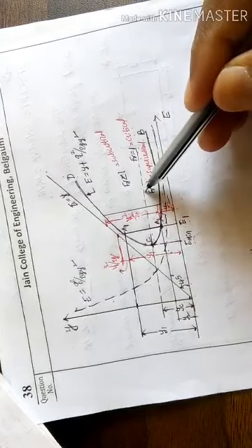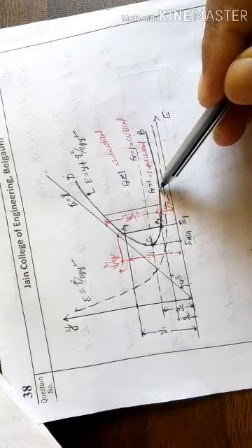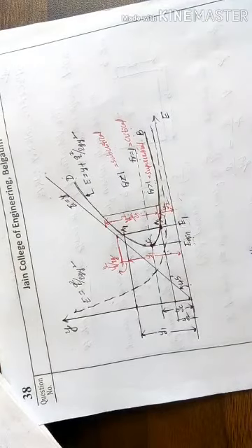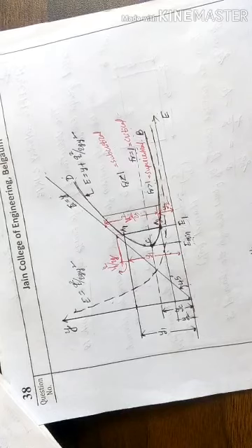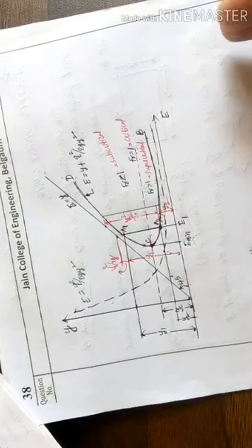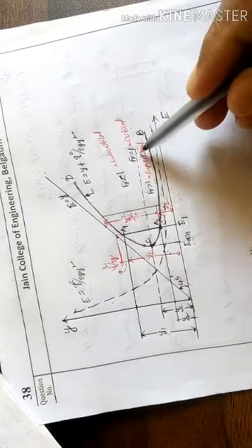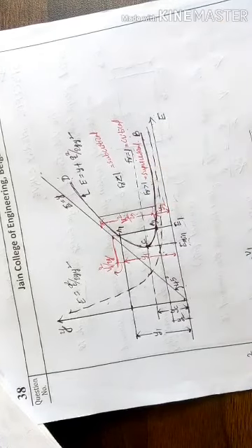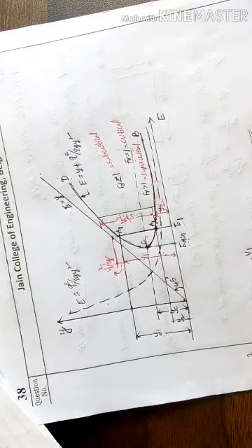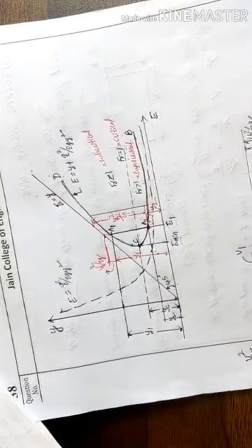So if the depth is below critical, obviously the velocity of flow is very high. When the velocity is very high in a channel, that type of flow represents high velocity flow or rapid flow, or it can be classified according to Froude as supercritical flow. If the depth of flow is high, the velocity is less.